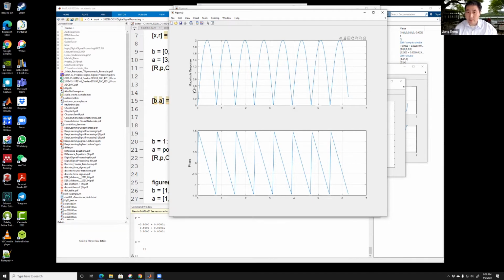So if you remember last time, let me just write here. This H(z) is equal to 1 subtract z to the power -8. That's it. I only have the numerator. I do not have the denominator. The coefficient B is 1, then zeros, and then a -1 at the eighth position. And A is just 1. So if you put this as a vector in MATLAB, A is a vector, it's 1. So I don't have a denominator. That gives me this one.